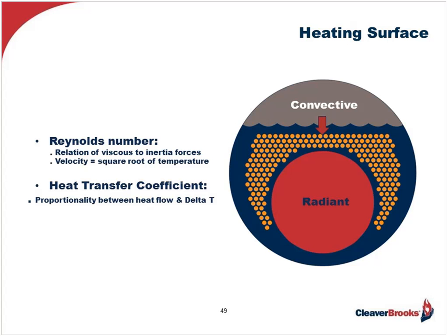the Reynolds numbers, which is the ratio of inertia forces to viscous forces. And to a large extent, this dynamic is dependent on the velocity of the gas passing through the heat transfer surfaces. For instance, with velocity being the square root of its temperature, a value of less than 2,000 equals laminar or viscous, and a value of over 4,000 equals turbulent, and as such, a much better conductor of heat. The more turbulent, the better the conductive heat transfer across the metal surfaces.